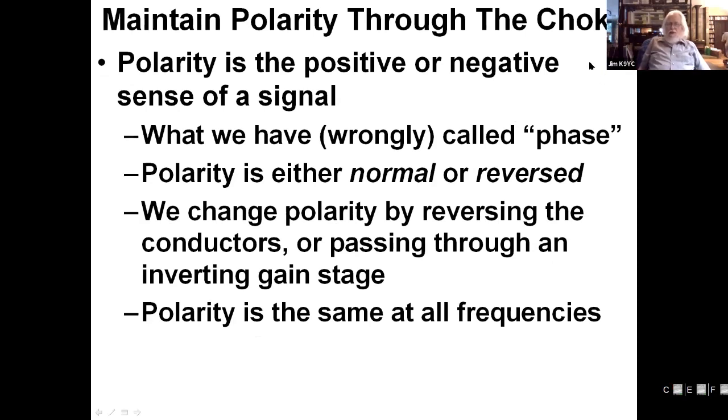Let's talk about this word polarity, because it's kind of new to hams. We had to learn about it in pro audio because having it wrong was a more severe train wreck than in the ham world. Polarity is the positive or negative sense of a signal, what we have wrongly called phase. Polarity is either normal or reversed. We change polarity by reversing the conductors or by passing through an inverted gain stage. Polarity is the same for all frequencies.